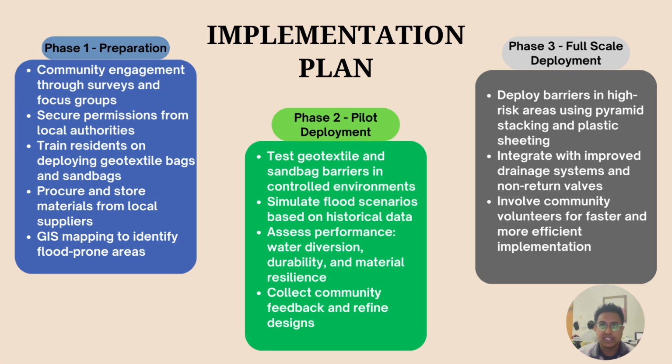Okay, for the phase 3 is full-scale deployment, which is deploy barriers in high-risk areas using pyramid stacking and plastic sheeting. The geotextile and sandbags are integrated with improved drainage system and non-return valve. Involve community volunteers for faster and more efficient implementation.